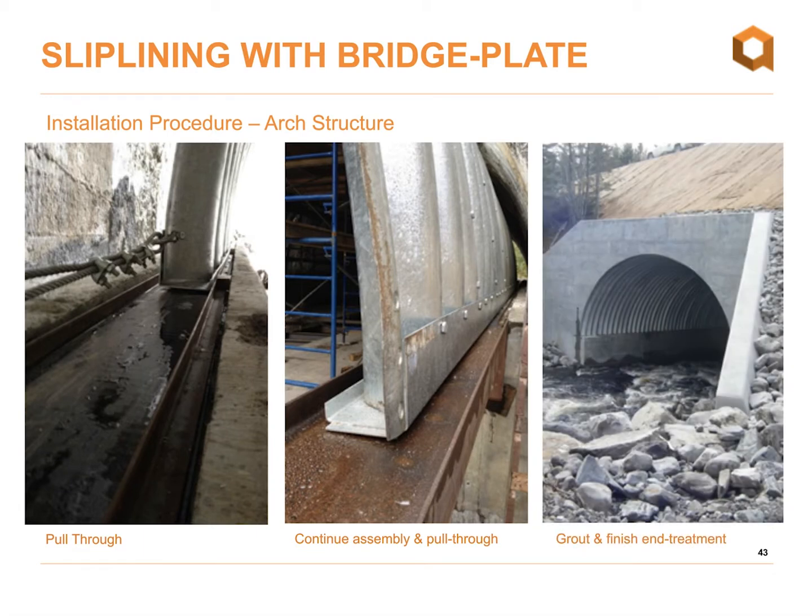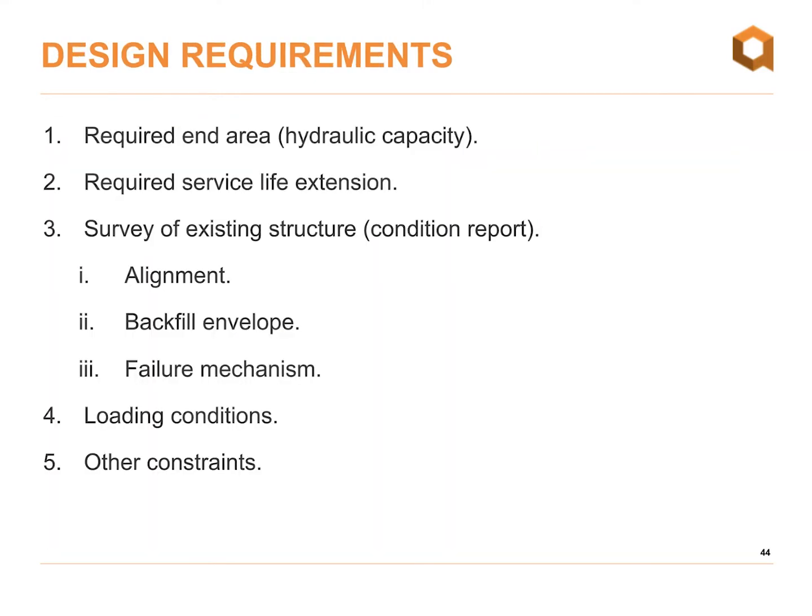They elected to put a cast-in-place head wall on the end here. Again, it's one of the best methods of protecting the structure from certain failure mechanisms like scour and piping and those sorts of things.